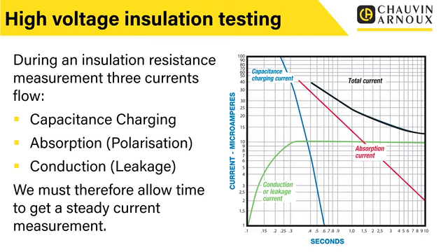But the good thing is, as you'll see when we actually get into the testing techniques, we can use these to our advantage. We can use these charging currents and the fact that this is a known state, and we can use this to tell us about the state of the insulation as well, which is really good. When we start looking at testing techniques, you'll see how we actually use this. The fact that it starts off and the currents are changing, and then we get to a steady state, we can use that to tell us a bit more about the condition of the insulation.